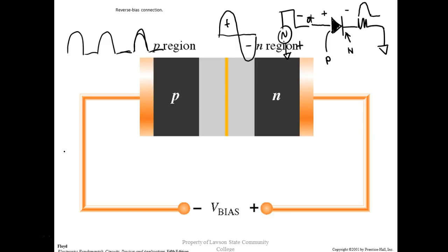So a rectifier is a circuit that converts what? AC to DC. This is pulsating DC. I wouldn't put this on my stereo. It would hum a lot, right? You understand? But this is our first step from going from one. And this diode does it automatically. It does that switching. When it's forward, but when it's reverse bias, it cuts off. When it's forward bias, it cuts on. Off, on, off, on. And we can do this with AC.